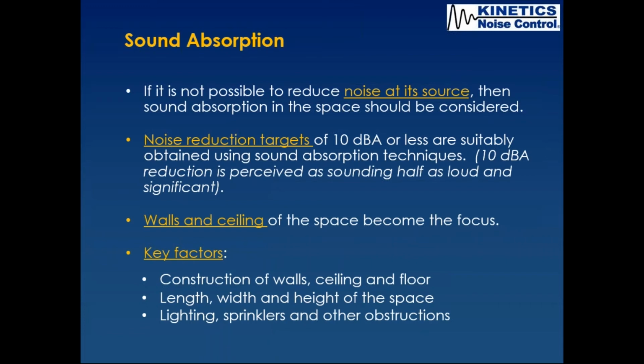And in that case, if you're looking at a 10 dBA type noise reduction, or maybe a 5, 6, or 8 dBA, somewhere in that range, sound absorption alone can often obtain those noise reduction levels. And remember though, 10 dBA, some of you might say, doesn't sound like it's going to be a huge noise reduction, but since it's logarithmic, the human perception of sound, anytime you have a 10 dBA noise reduction, to the average person with average hearing, it's going to be perceived as sounding half as loud.